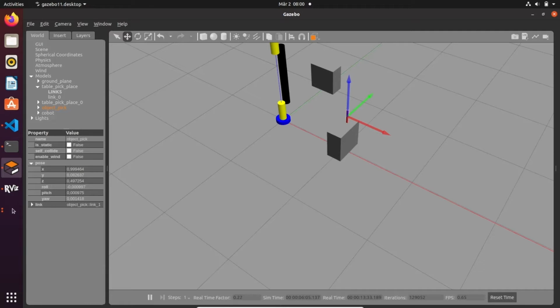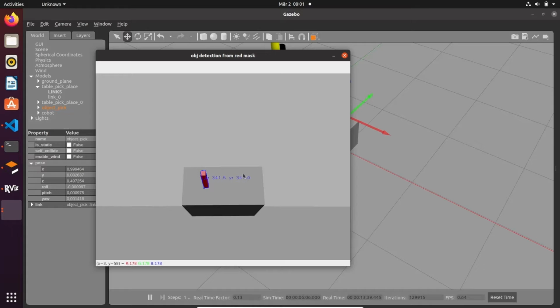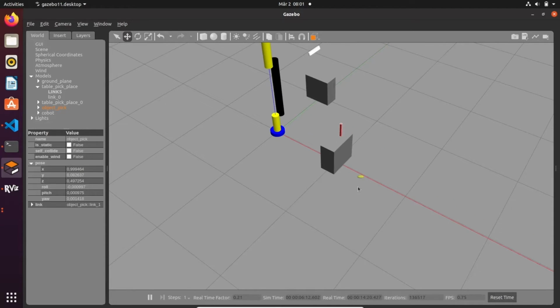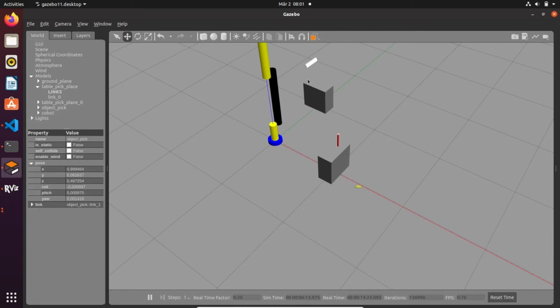So this is the first thing. The second thing is that due to the fact that the camera is positioned here, you are gonna have the center of this rectangle that is an offset with respect of the top of the object, and if we convert this coordinate into the frame coordinate of our environment, we are gonna get a different value. So we will need to find a way to somehow downsize our application from 3D to 2D.